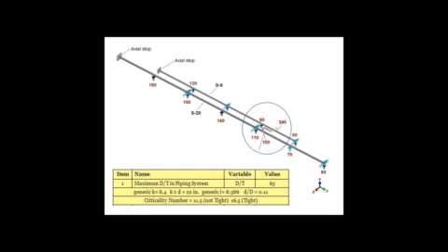If we go next to the next system, this is another typical problem where you've got long sections of pipe and small crossovers. The SIFs and the flexibilities of the small crossovers can be a little bit important when the piping is tight. Here we see D over T values of 63, criticality numbers of 11 to 16 if it's tight. That's a little bit over where we want to go.